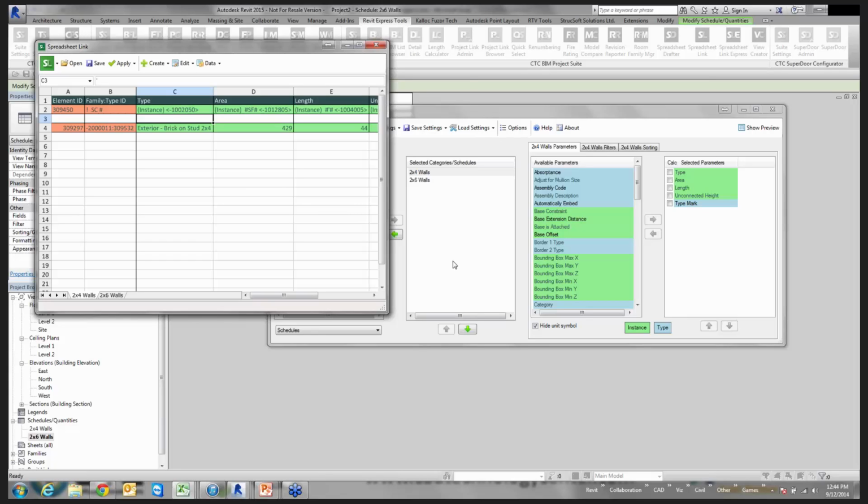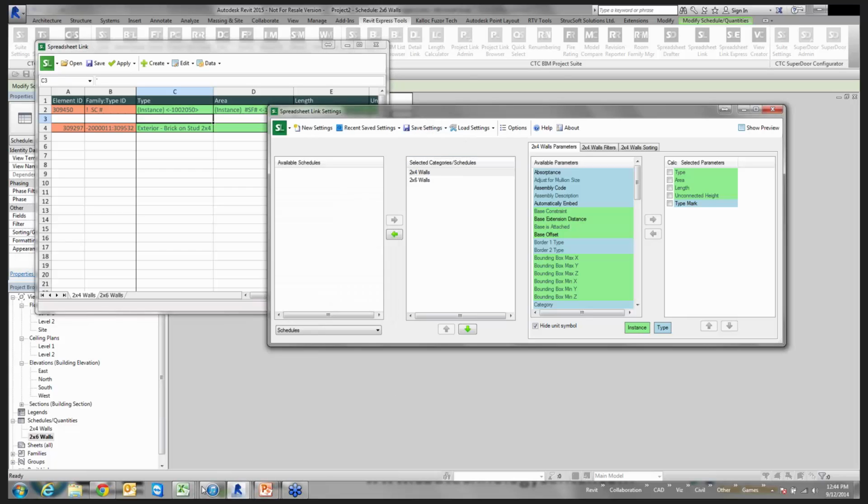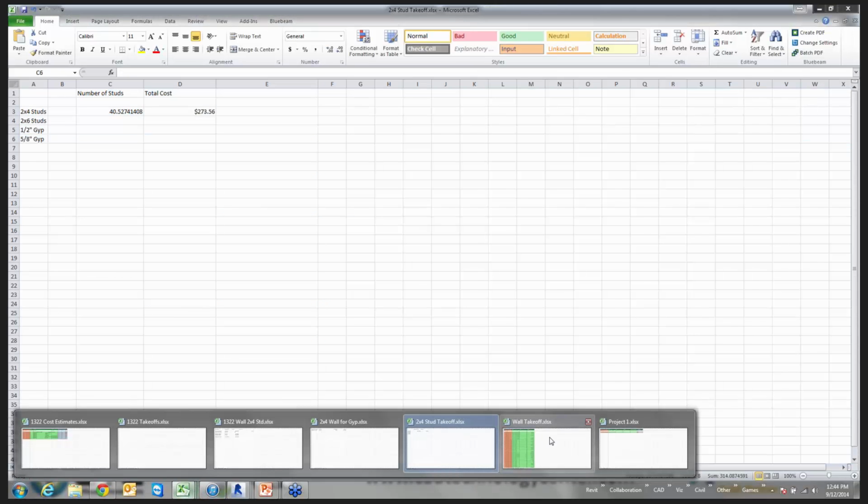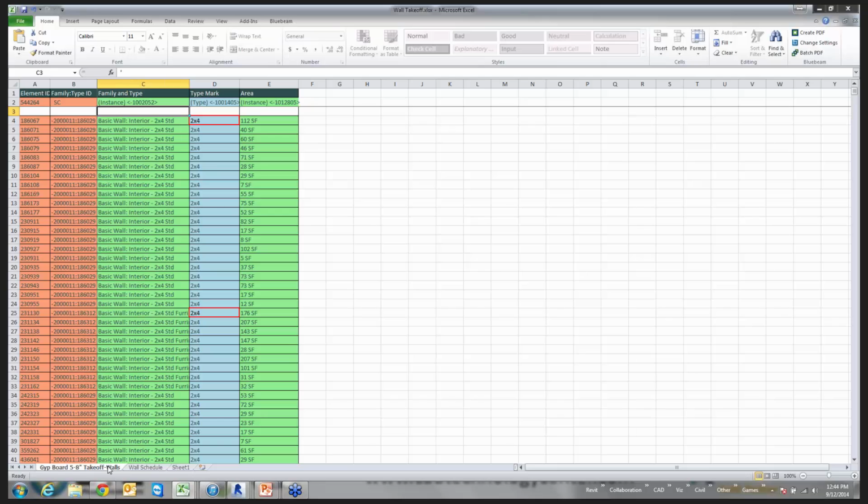I mean, certain ways to set it up inside of Revit to simplify the process, to bring it back into Excel via Spreadsheet Link. And again, the primary benefit to this is getting it all grouped into one location, so that you don't have 15 different files to work with. It's a little bit more familiar to the person who's actually going to be doing the quantifications out of this. It's all in one location, a series of workbooks, one page full of all your formulas and data that they need to bring into their cost estimating software.